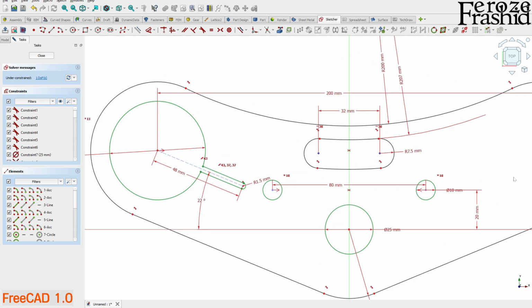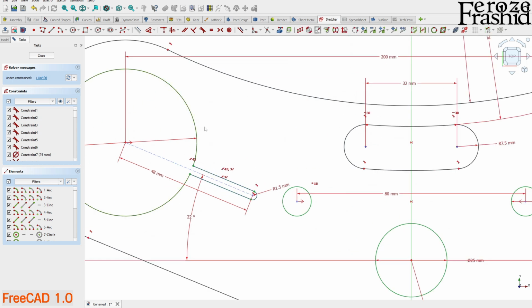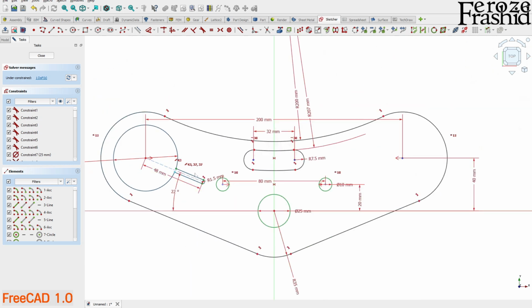I want to mirror it over on the other side. So take everything, double click on the edge, which adds anything connected, and also take this construction line and move it over to here. So that's mirroring it over. We have the mirror button here.